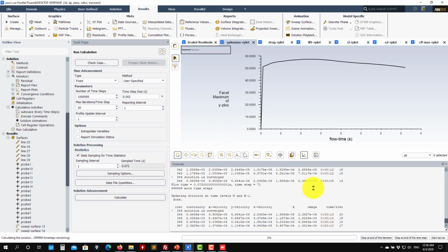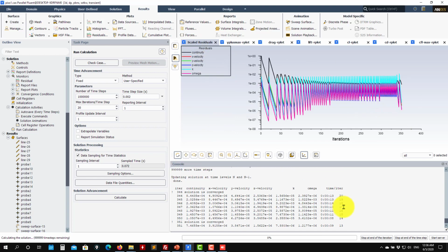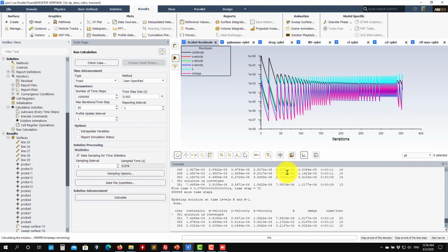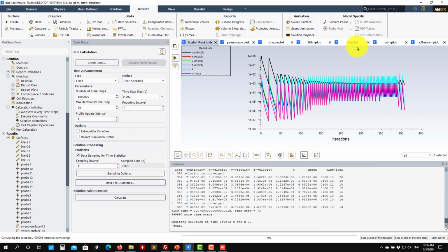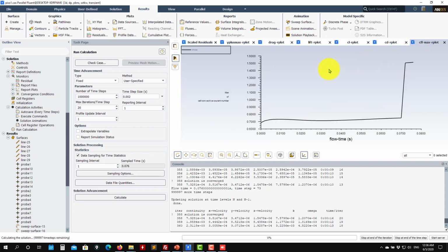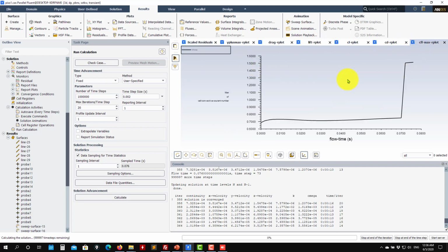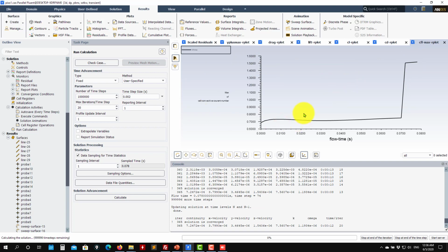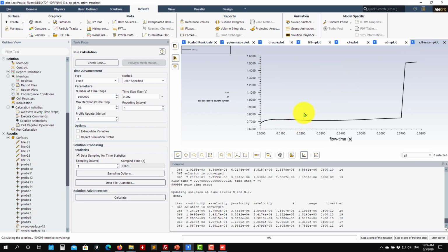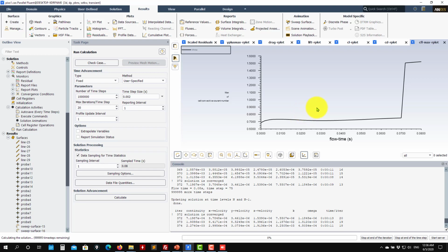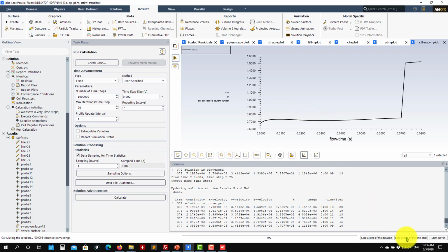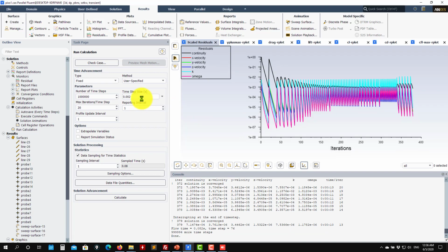Immediately see that now it's taking longer to converge. Still it is within that value now, 0.48 iterations. And see the CFL, it is double. Okay, it's almost proportional. You double here, you double your CFL number. And still we can go higher. So let's put it 0.5. Okay, so I will advance more